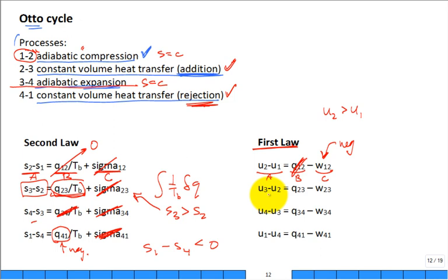Okay. Now let's maybe jump to the third one because it's also adiabatic expansion. So let's jump to this one. This is our third process from 3 to 4. Isn't it adiabatic? Now it's expansion. So is the work 3 to 4 positive or negative? If it's positive, but you have the negative sign in front of it in the first law, so what about the final U4 is less than U3? The internal energy goes down. It's less internal energy at the end of that process.